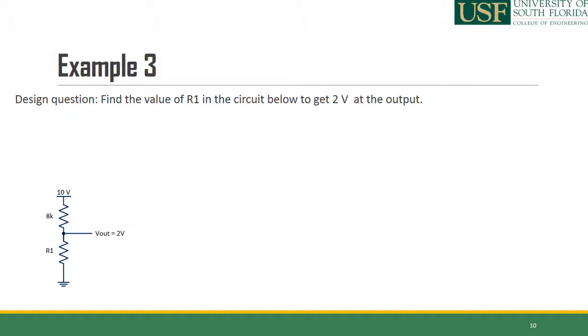So assuming you have a 10 volt power supply and you need 2 volts for a part of the circuit as a reference or whatsoever, and you're wondering how you can design the circuit to convert 10 volts to 2 volts. I'm not saying that this application works for every voltage change, but for certain cases, if you know that the answer should be done by the voltage divider, we can simply choose 2 resistors that bring the voltage of the 10 volts to a lower value.